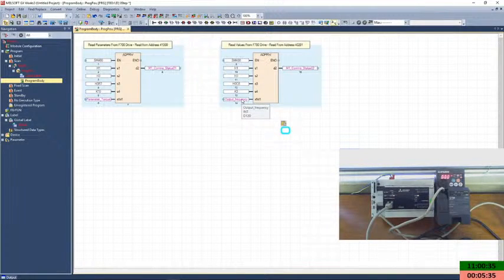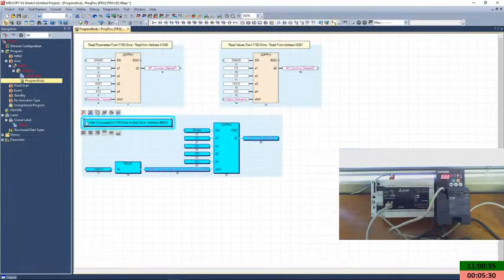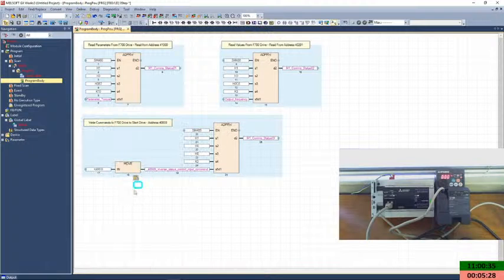Also we're reading, I showed you guys this a little bit earlier as well. And now we look at adding the write commands. We're going to write to address 40,014. So H6 means we are writing, that's the function code. And we're writing from K4M10, which basically means that you're writing the next 16 bits to the word. Of course, a word makes up 16 bits. So each bit from M10 up to M25, we're going to be writing into that word over there.